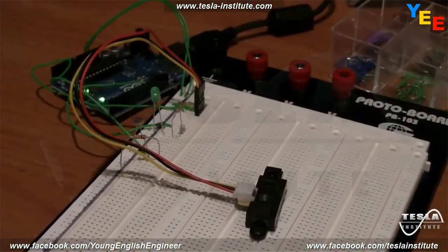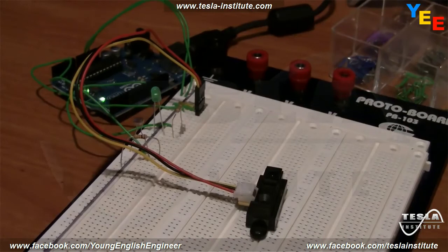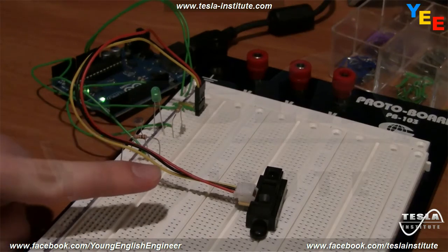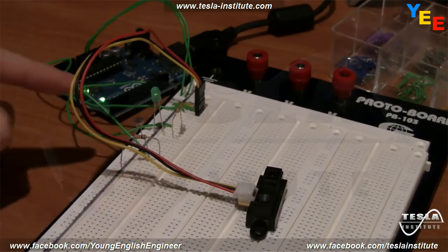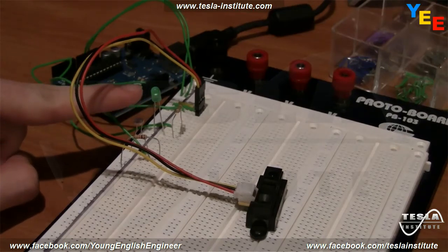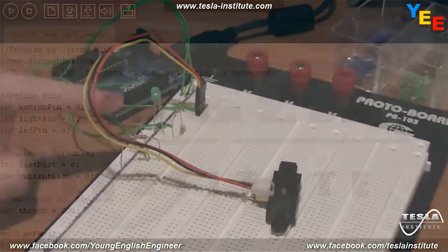Let's wrap up today's tutorial with our first little project. This project will combine the infrared distance sensor and the photodiode that we used today to make an emergency lighting system. In the event that a room is dark, detected by the photodiode, and movement is detected by looking at values from the infrared distance sensor, we'll turn on our emergency lighting system, in this case an LED.